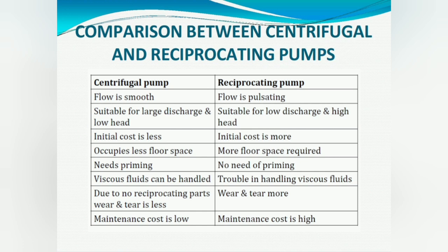Priming is mandatory for centrifugal pump and no priming is necessary for reciprocating. Viscous fluids can be handled in case of centrifugal pump and it is facing some trouble for reciprocating. Due to no reciprocating parts, the wear and tear is less. And wear and tear are more in case of reciprocating pump. The maintenance cost is low for centrifugal, whereas the maintenance cost is high for reciprocating.